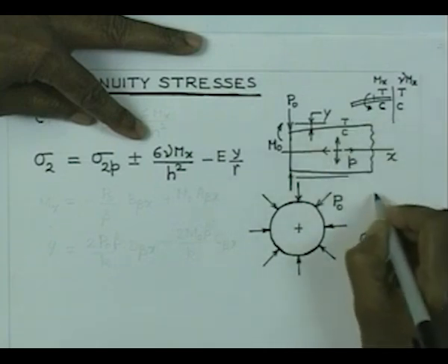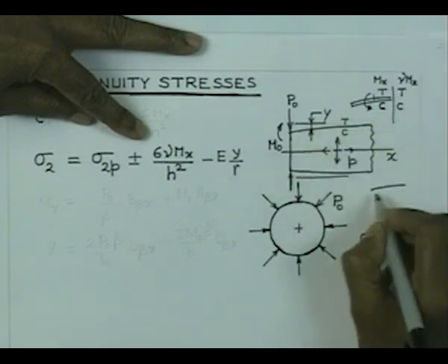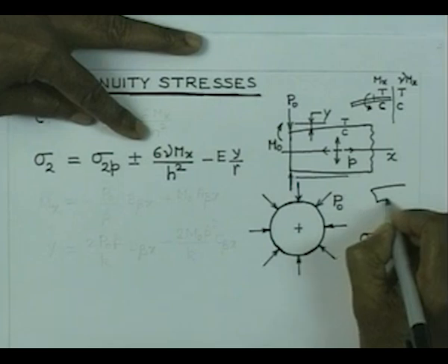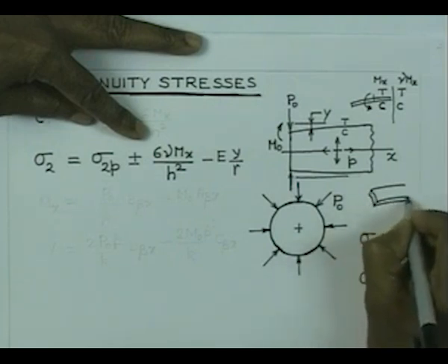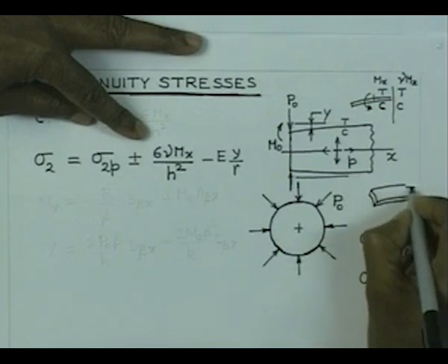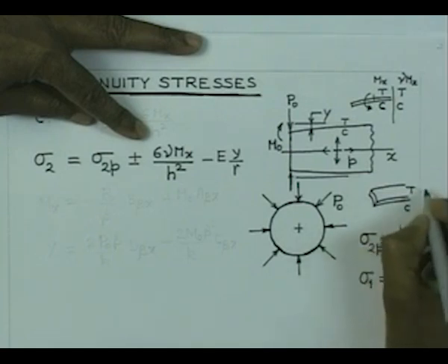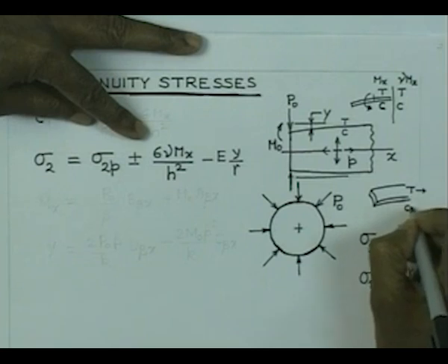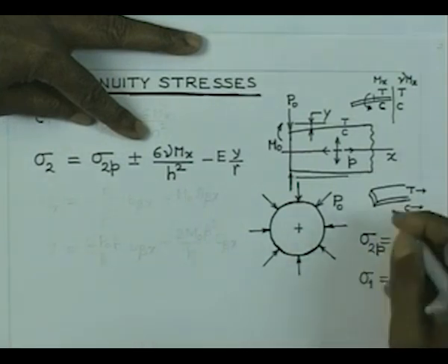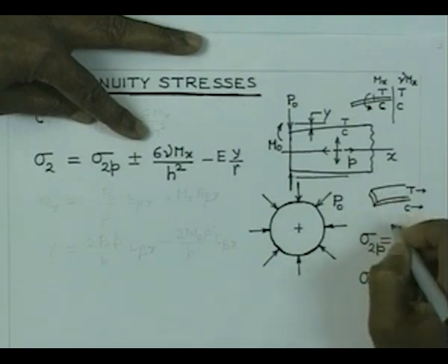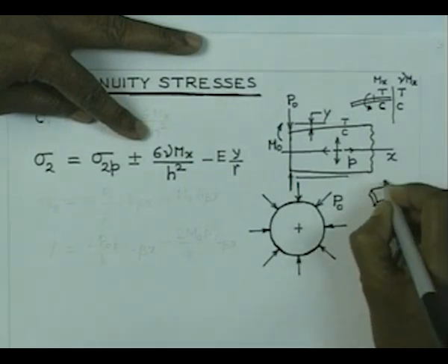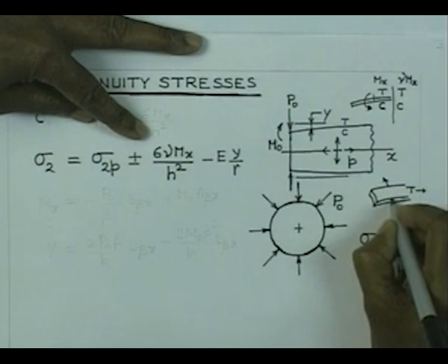Think for a moment that when this cell is bending like this, you are going to get tensile stress there, compressive stress there in the axial direction. This is in the axial direction, let me show it that way. Now, since it is trying to elongate in this direction, it will try to contract in this direction, and the material on this side and on the other side will try to prevent contraction, and therefore, it will try to again generate tension here at the top fiber.